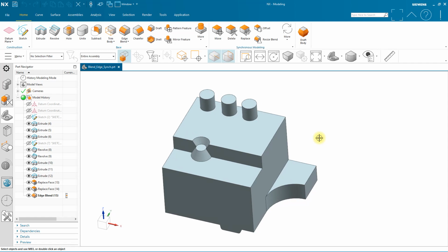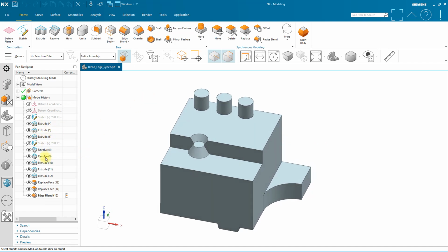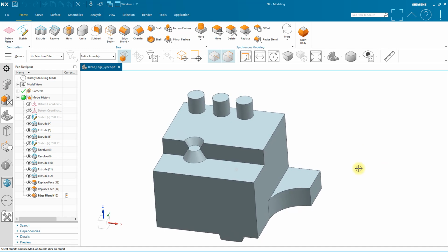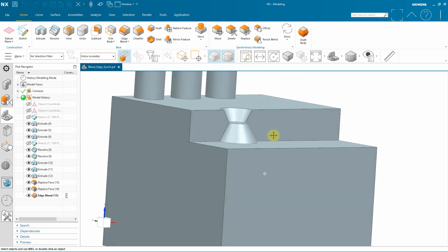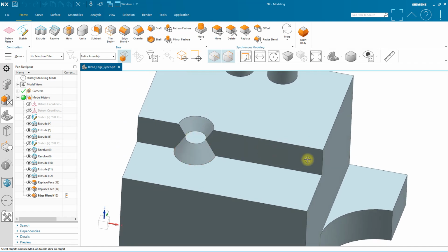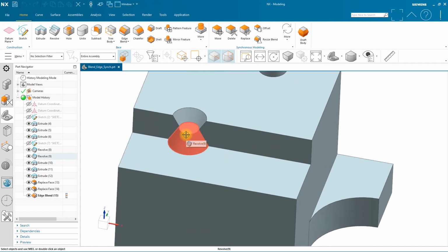These tools allow me to just directly edit on top of whatever is in front of me, whether it's imported or even if it does have a feature tree. For example, if I take this little conical boss here, and I simply just want to move it. Let's say I have to figure out, okay, where's the dimension that drives the location of this boss?